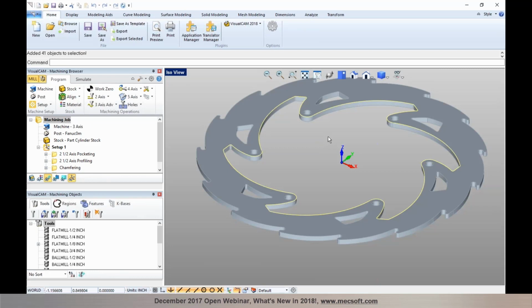Now you can also select multiple of these by holding down the Shift and Control keys. I can go back and select another edge, and you'll notice that it automatically selected the chain for the interior. We were also able to select the exterior of this particular part. This is one of the very nice enhancements in Visual CAD where you can make your workflow a lot faster, selecting a chain of curves or a chain of face edges or surface edges from your solid surface geometry.